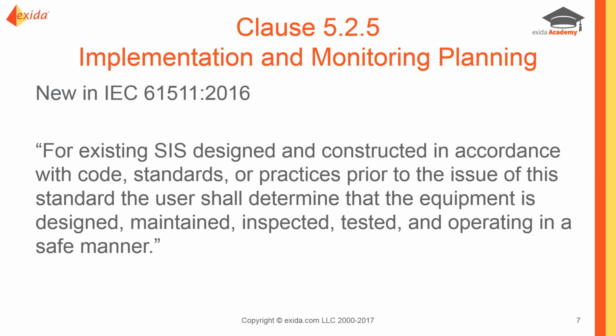In the new version of IEC 61511, they've actually beefed up the instruction a little bit, and this is the actual language out of the standard that you're seeing on the slide for implementation and monitoring planning. When they refer to everything should be operating in a safe manner, what that means is no dangerous failures within 12 months. And this is a new version of IEC 61511.